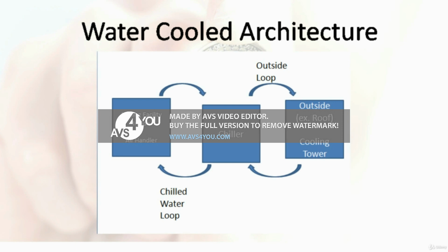In comparison to using an air conditioner in the air-cooled architecture, the cooling unit in this architecture is usually an air handler instead. They have the same general function, however. They do it quite differently. The cooled water in an air handler is moved through a coil, and to get the heat withdrawn, the cooled water is heated and then pumped back to the chiller. As in the case of what you see in front of you right now, the chiller is just a heat exchanger between the facility and the external refrigerant loop, where the main goal is to transfer the heat to the air outside.